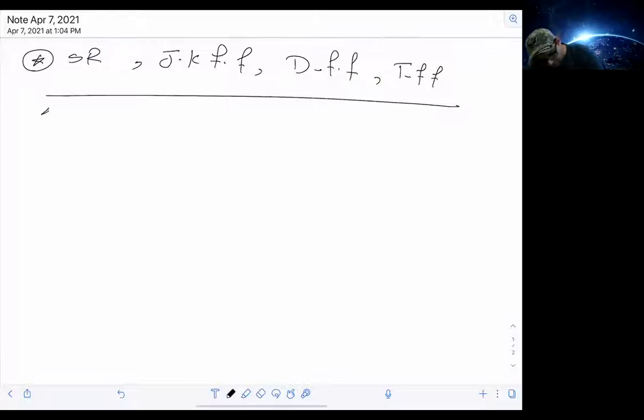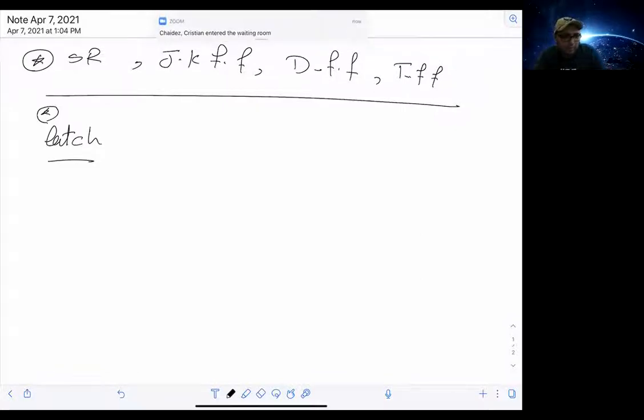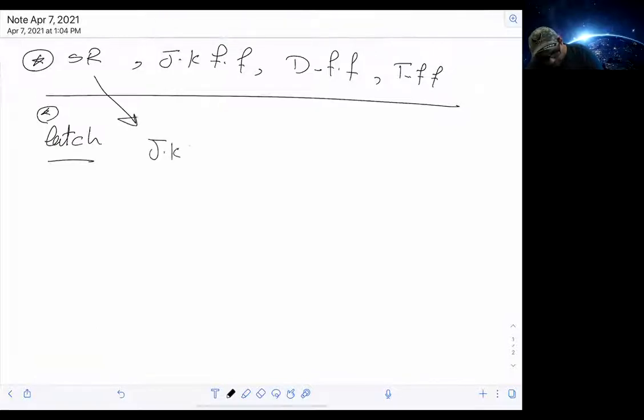What we learn out of it, we learn the story coming from the latch, right? And on top of that, we came to the conclusion to fix the problem with the SR by building the JK flip-flop. And traditionally, the JK flip-flop introduced a new problem, which is the oscillation, that was fixed by adding an extra cascaded latch reporting on the opposite of the edge of the clock.